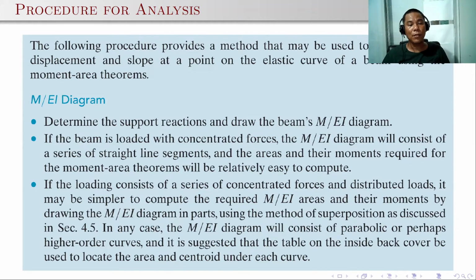If the loading consists of a series of concentrated forces and distributed loads, it may be simpler to compute the required M over EI areas and their moments by drawing the M over EI diagram in parts using the method of superposition. So this is what I was saying earlier.